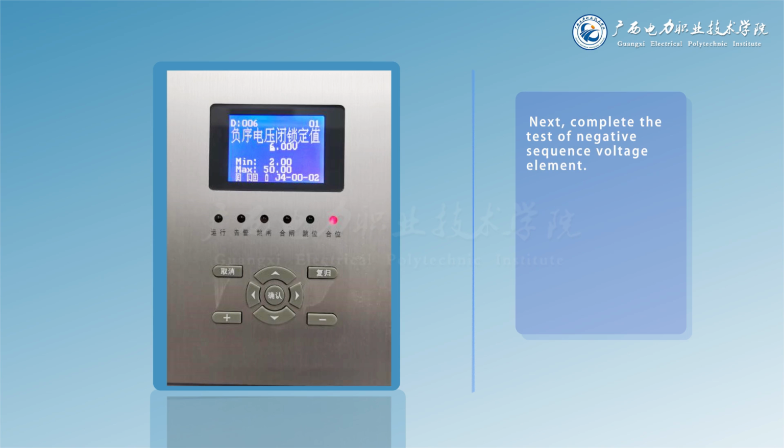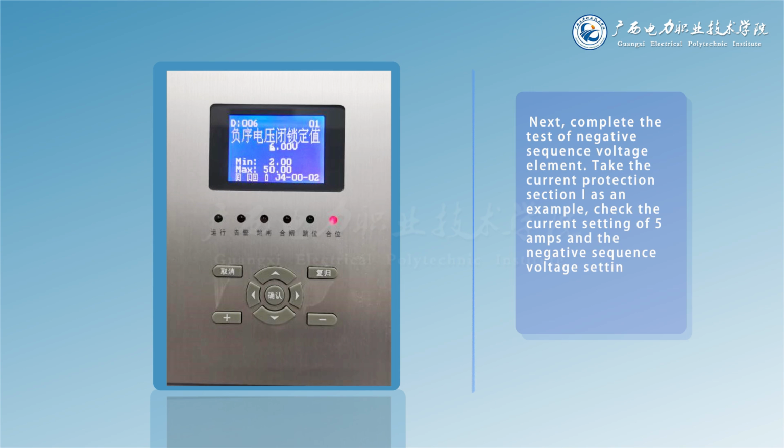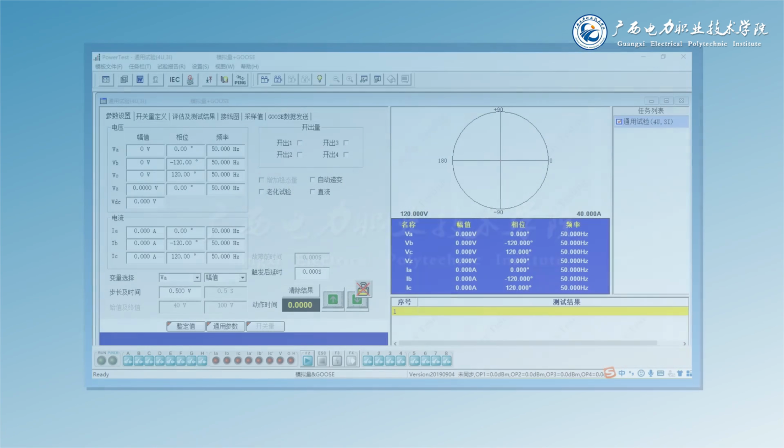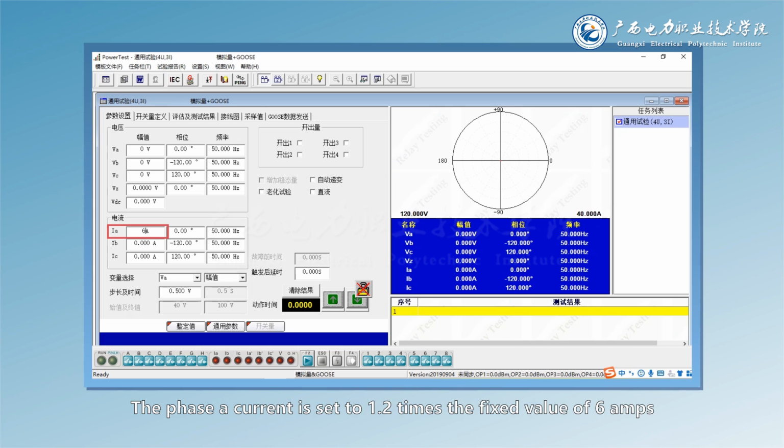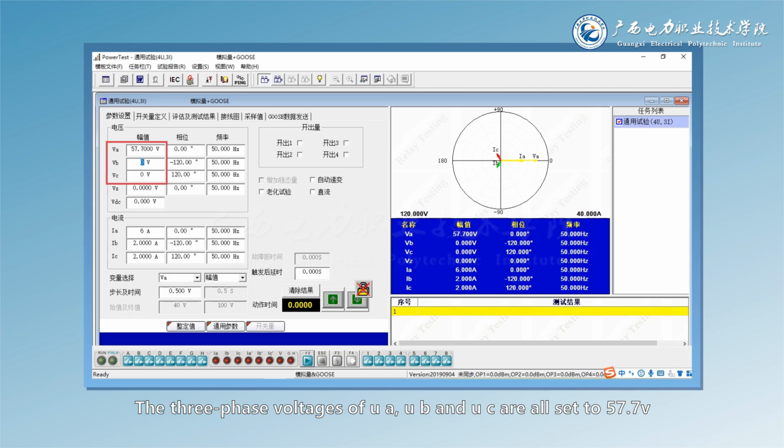Next, complete the test of the negative sequence voltage element. Take the current protection section I as an example. Check the current setting of 5 amps and the negative sequence voltage setting of 6V, and put into protection. In the general experiment, we simulate the test under A phase fault. The A phase current is set to 1.2 times the fixed value, 6 amps. The B and C phases are set to a load current of 2 amps. Positive sequence. The three-phase voltages of UA, UB, and UC are all set to 57.7 V.